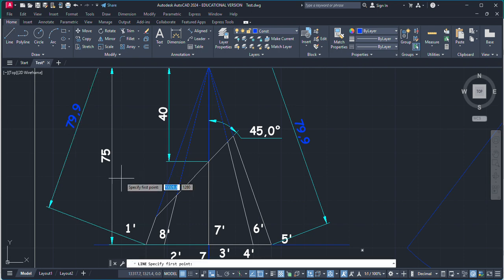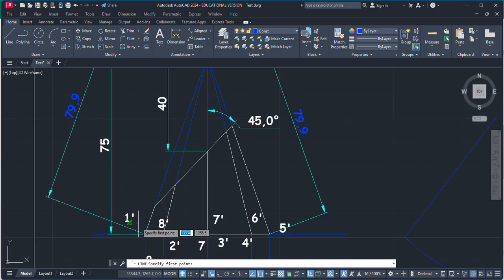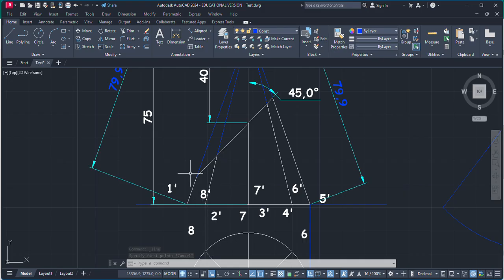So what I'm going to do, we will measure this segment. This is the actual dimension, because this 1 dash O dash represents the actual length of the slant edge, as they are on the same horizontal line. But 2, 3, 4 are not on the same horizontal line with O, so these are not correct. This one is the actual length and this one is the actual length, but these three are not. So to measure these, we will use either this one or this one. I'm going to measure these two in terms of this right one and this third.